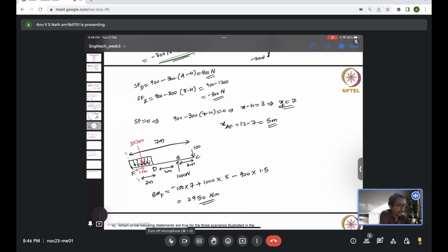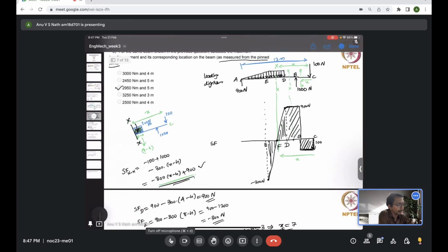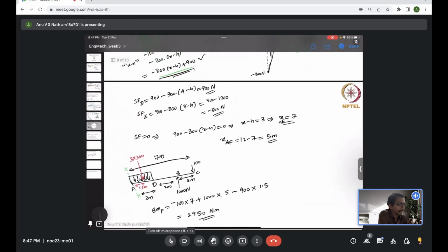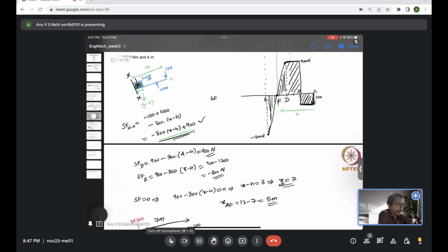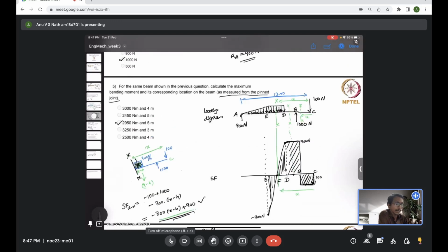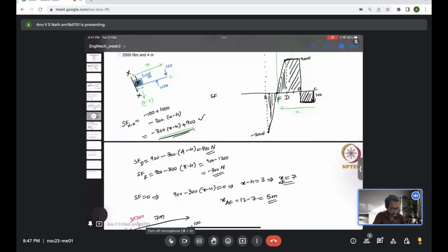So this is a little bigger question. So whatever asked in the question, we can just do this, like stopping the shear force diagram somewhere in the middle and only using the data from that much to evaluate and reach the final solution. But I suggest you to complete the shear force diagram in the remaining area. So remember, now you have a UVL and varying load, which is a linear variation. So its integral, which will be quadratic, that is the shear force diagram. So if you draw, you will get something. I have the solution, I can draw that.